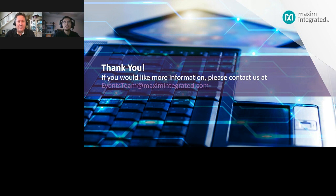Yeah, essentially, there's no extra code that you need to develop, but you have the option of enabling or disabling it, especially in SRAM. For the 3 micros that we talked about, the flash ECC is always on. But in the SRAM, you have the option of disabling or enabling it, and this is done through a bit that you set during your development.